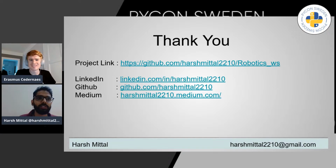Yeah, so there's one thing called rosbag. All the different data that is coming on all the different topics, you can actually record. It is done in real time, and it will be collected in a single file. You can send that file to anyone who wants to simulate that, and they can run that particular rosbag file, and it will behave as if it were actual hardware sending all that data.